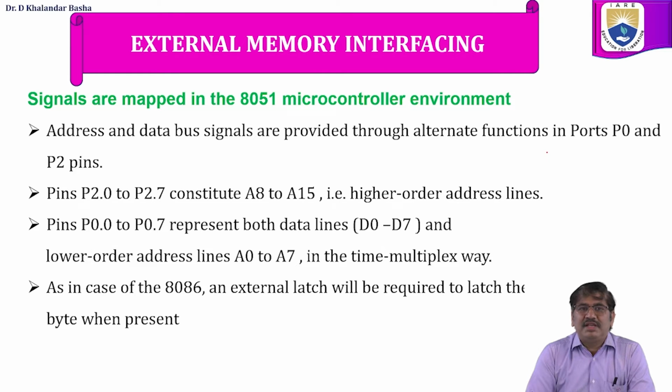We can call this the higher order address lines. Port 0 bit 0 to bit 7 represents both data as well as address information, that is AD0 to AD7.